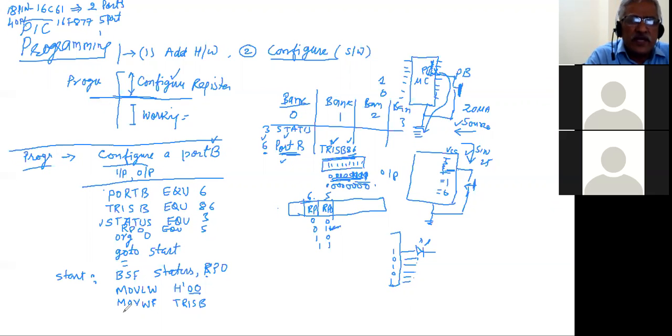So now if I write anything on the port B, that will be outputted onto these lines. Let us say I can directly write move a literal into the accumulator, and let us write the literal as hexadecimal value 55. What is the meaning of 55?